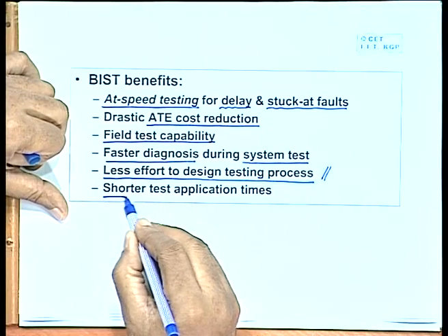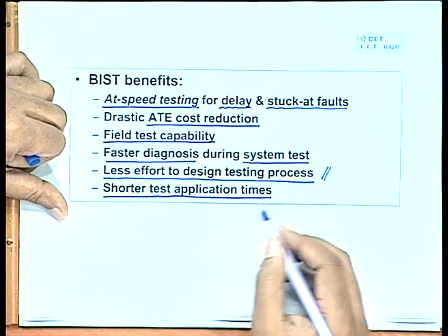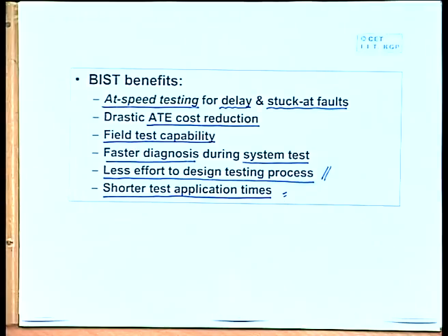And of course, shorter test application time, because everything is done inside the chip and at a very high frequency, the total test application time also gets reduced. Okay. So, we have looked at some schemes for, of course, earlier we talked about methods like test generation and fault simulation.